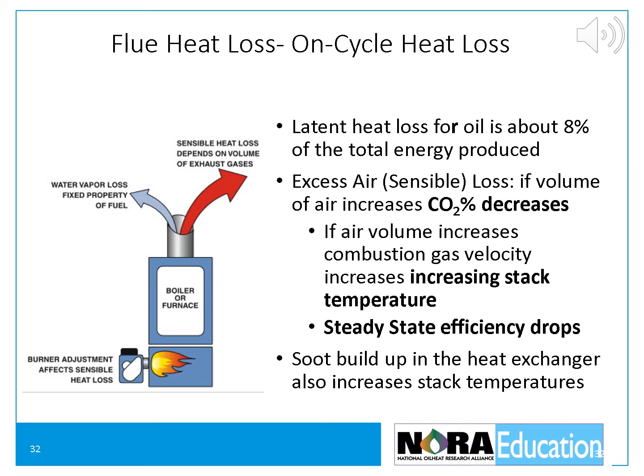The performance of older systems could be improved significantly by replacing the burner with a new flame retention model. However, the most effective way to reduce excess air heat losses is with a new boiler or furnace. New appliances operate very efficiently with on-cycle losses ranging from 9 to 14%.